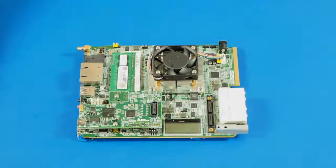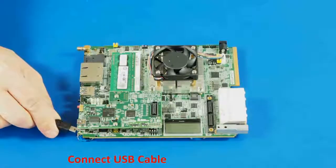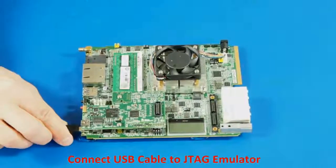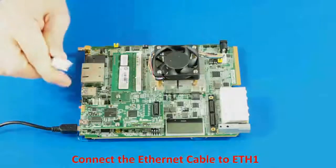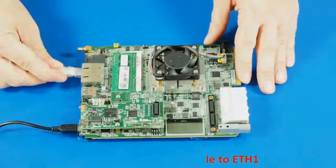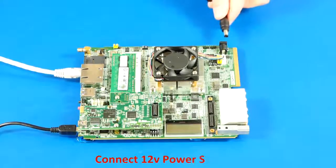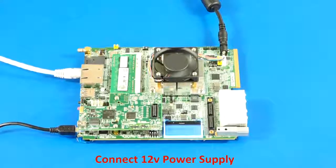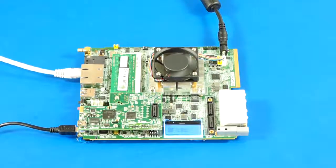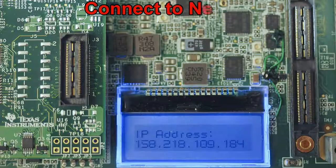The EVMK2H is designed for quick and easy setup out of the box. Simply connect the USB cable to the onboard JTAG emulator, connect the Ethernet cable, and insert the power cable. Connect EVM Ethernet port 0 to a corporate or local network running DHCP.